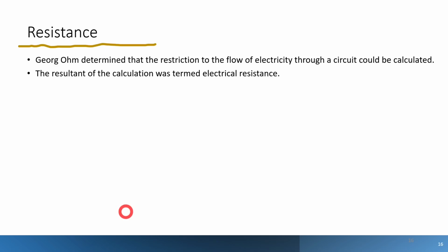So a small short copper wire has more or less electrical resistance in it than one that is the same diameter but much longer. And that makes sense that you want the wires for jump starting a car from car to car not to be 100-foot wires, because you're going to lose voltage. There's going to be a voltage drop in that wire if they're pretty long. That's why most of them are 6, 8, 10 feet long, just to keep any voltage drop from occurring.